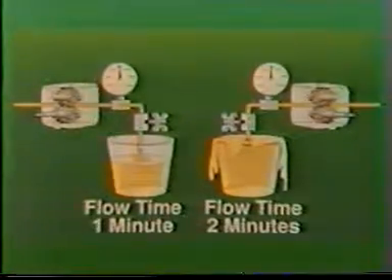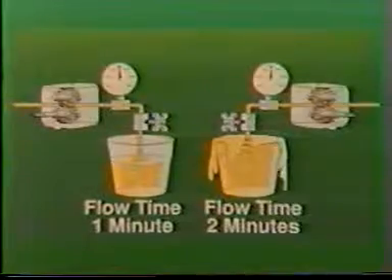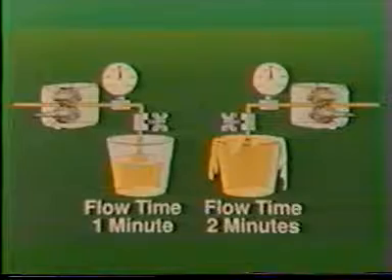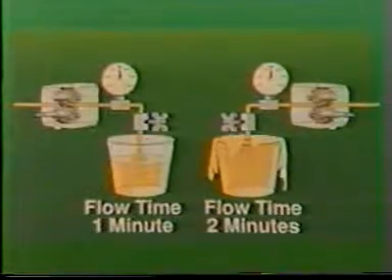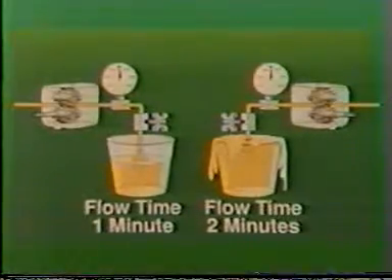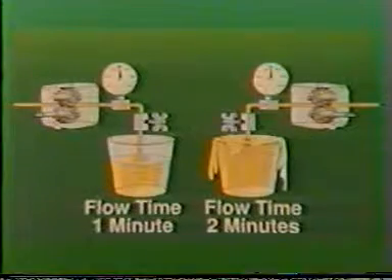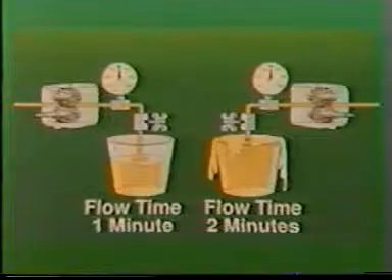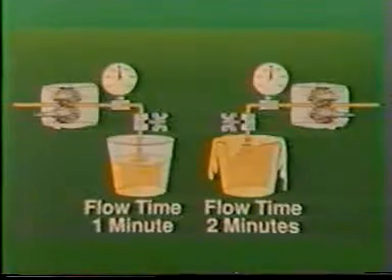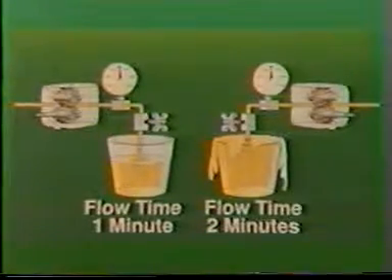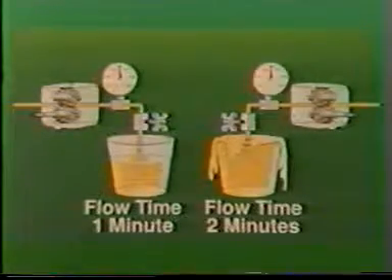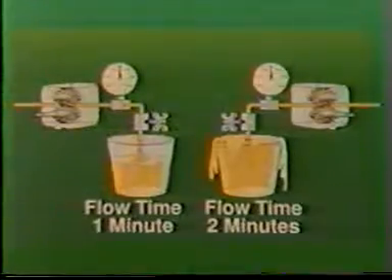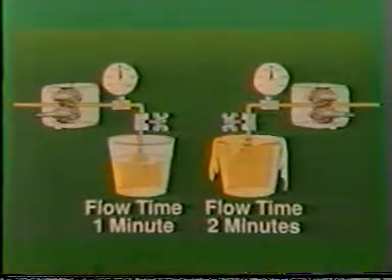Finally, if passages of equal flow area are connected to equal sources of pressure, the time the fluid is allowed to flow will determine the amount of fluid collected. Thus, if the flow area and fluid pressure are held constant, the time determines the amount of fluid collected. These three illustrations provide an excellent example of the pressure time concept used in the QSK-19 fuel system, rail, and timing systems.